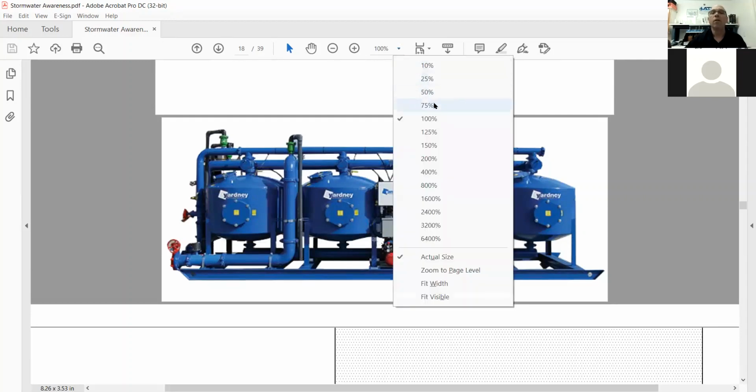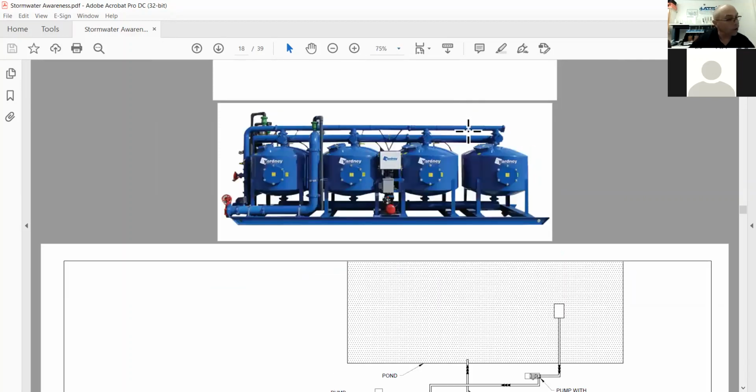Now I'm going to lower this size a little bit for the next pictures coming through. So, water system footprint requirements. A typical 200 gallon per minute system with one tank, that's using a 20-foot container and a standard size filter, will need to be about 800 square feet. And the shape of the pad will be based on site constraints, but we'll need room for a tank that's 40 feet long and 10 feet wide.